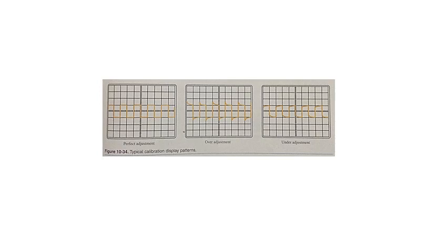The voltage, time period, and wave shape are provided by the scope as a perfect reference for the calibration operation. A square wave will appear on the screen. From this point, the appropriate adjustments can be made to make the wave on the screen match the expected reference wave. Most scopes use a 0.5 volt, 1000 Hz square wave as reference.